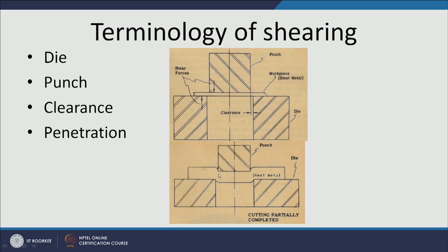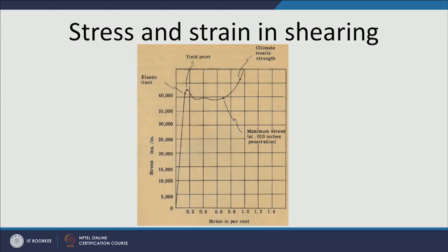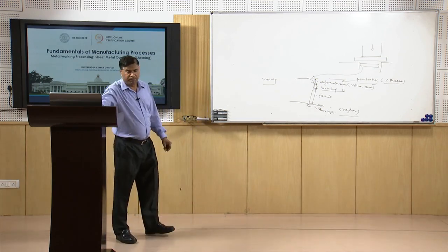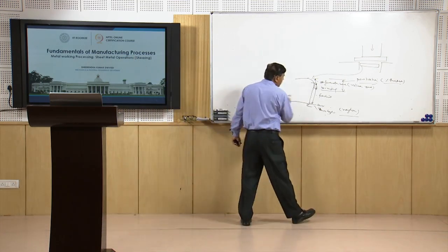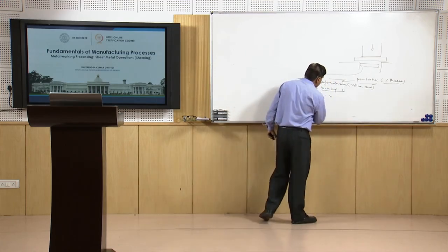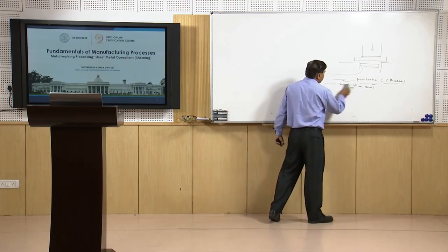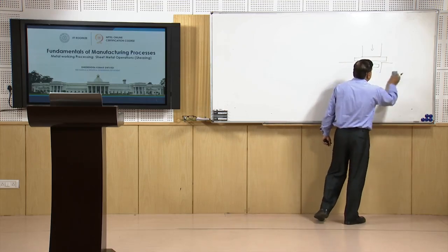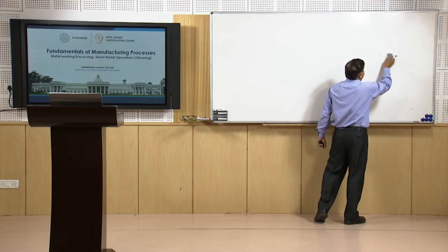This is what we can see, and this deformation leads to the development of compressive strains all along the circumference of the punch, and similarly compressive strains are also induced all along the lower edge of the die. So, when the compressive stresses are applied onto the sheet metal during the shearing, we know that when the punch moves down, the stresses onto the sheet metal will be increasing continuously, which will cause first the plastic deformation, and then it will lead to the penetration into the